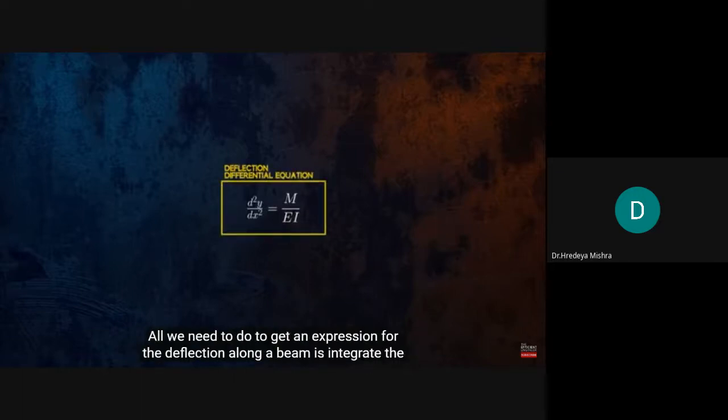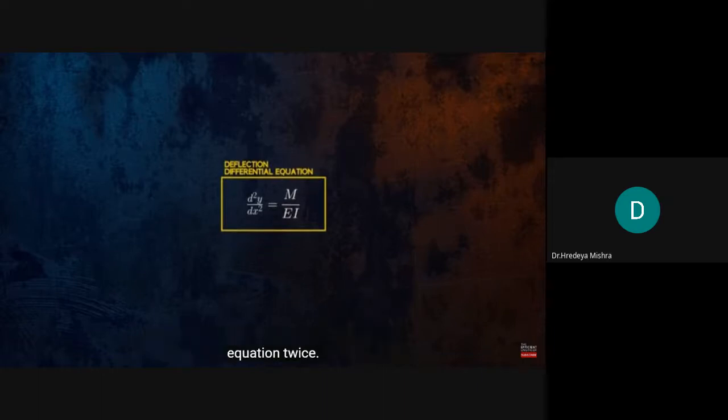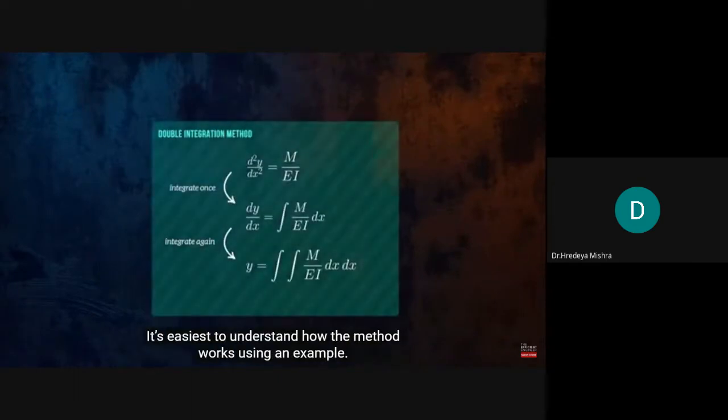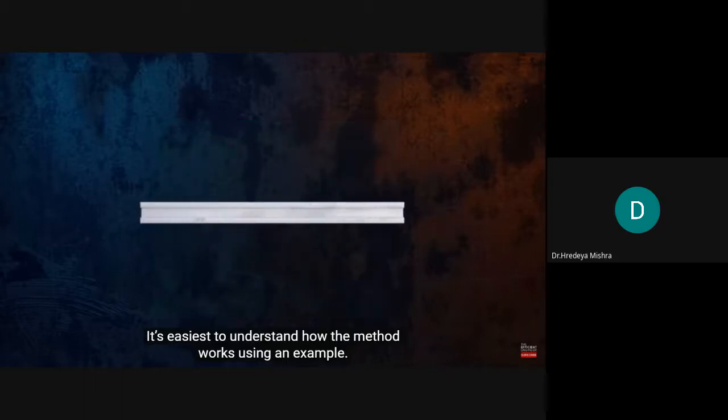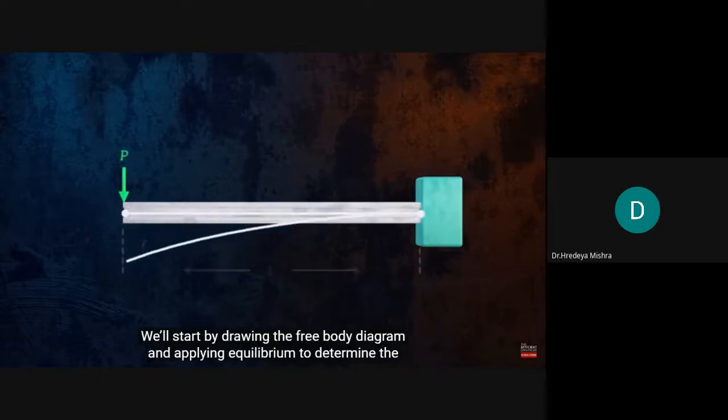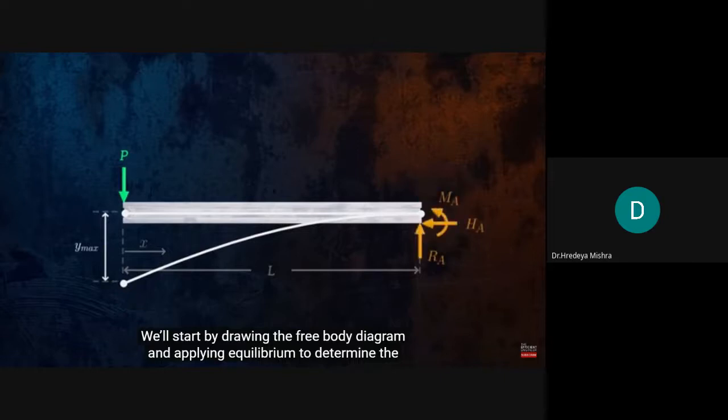All we need to do to get an expression for the deflection along a beam is integrate the equation twice. This is called the double integration method. It's easiest to understand how the method works using an example. Here we have a cantilever with a load applied at the end. We'll start by drawing the free body diagram and applying equilibrium to determine the reaction forces.